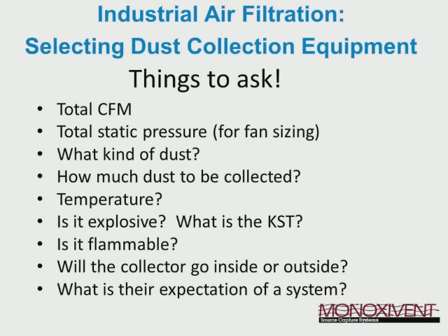Do you want the collector to go inside or outside? You know, it will take up a specific footprint. It may take up larger or more room than you have inside and you want to move it outside. We'll need to know that. And then what is the expectation of the system? Do you want this system just to get the majority of the dust, or do you want this system so clean that you can eat off the floor? So those are things to think about when you're designing a dust collection system.